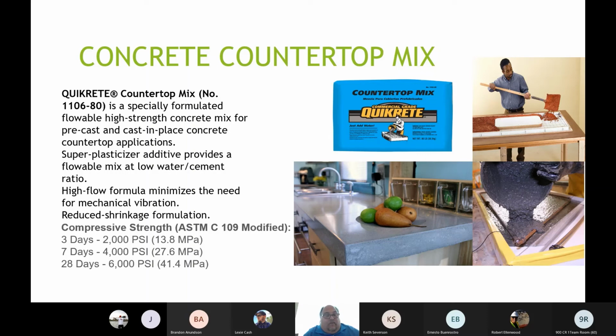If they're just doing a colored concrete countertop, a gray, a black, whatever, you add your integral color, you go to work, and the performance is fantastic, but the cost saving is unbelievable. And with the workability, you don't have to vibrate it as much. And that was another thing people were having problems with. They vibrated so much, it brings so much of that bleed water up to the top. It was leaving crazing, little chips and spalls, and a dusty finish when they started finishing it with the tools.